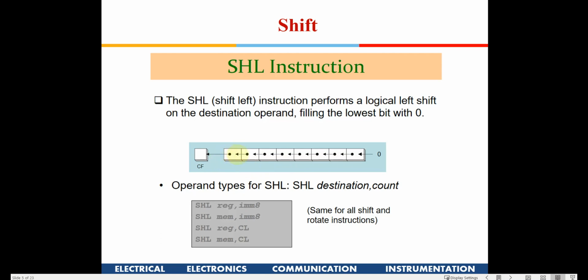Suppose you put all zeros here and you put only one 1 here, and then you take the output from one of the bits, pushing it into the input output port. Suppose this is running at 5 megahertz and you have 8 bits with all zeros and one 1. It will keep rotating like this, and the 1 will come back here after 8 clock cycles. So you get a clock frequency of 5 megahertz divided by 8.